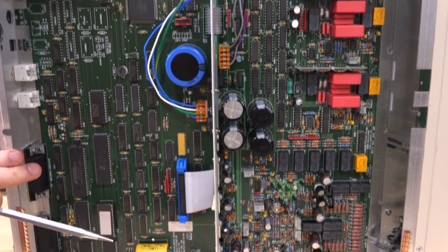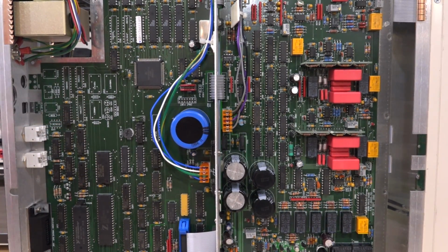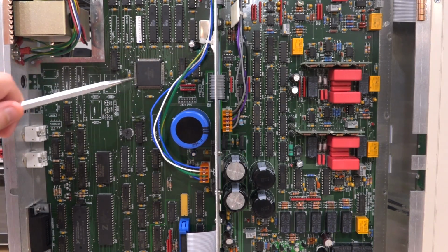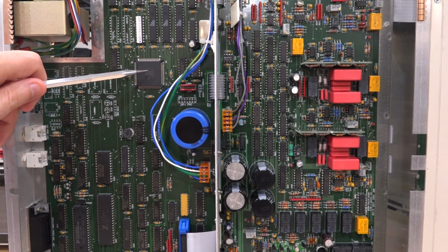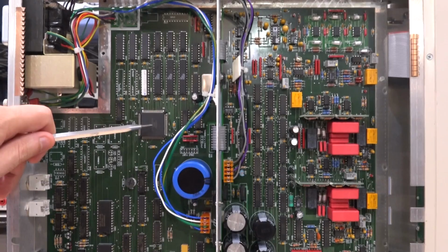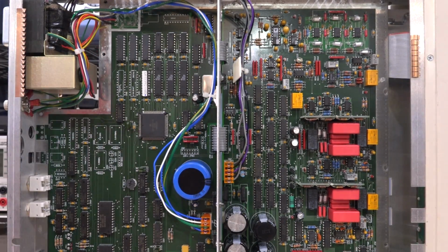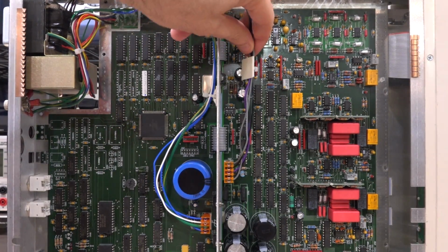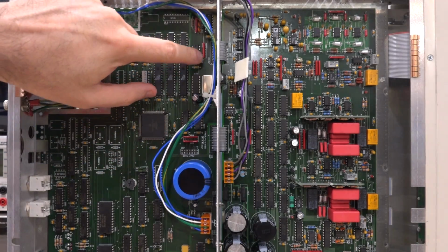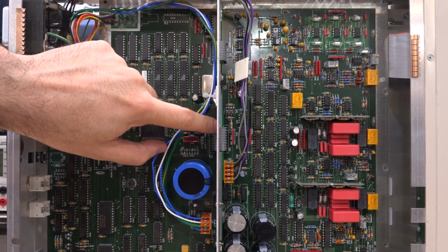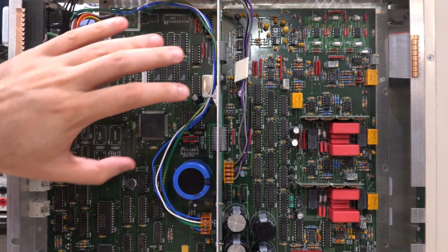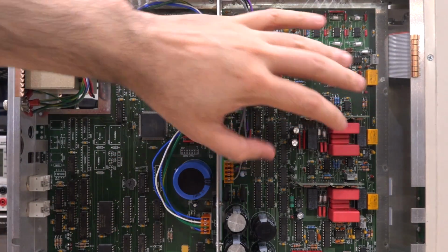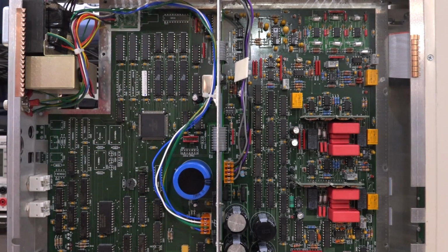There's some more logic and so on, some unpopulated stuff here because this thing does support an option with optical outputs, clearly made for audio applications, but we don't have that. Here's our Motorola DSP, which makes sense, that showed up inside of our block diagram, and then from there it feeds to the other side. There's a clever way of doing this. There's a ribbon cable here and a ribbon cable here that just jumps across. So the only way this board is talking to this board is through these two interfaces.